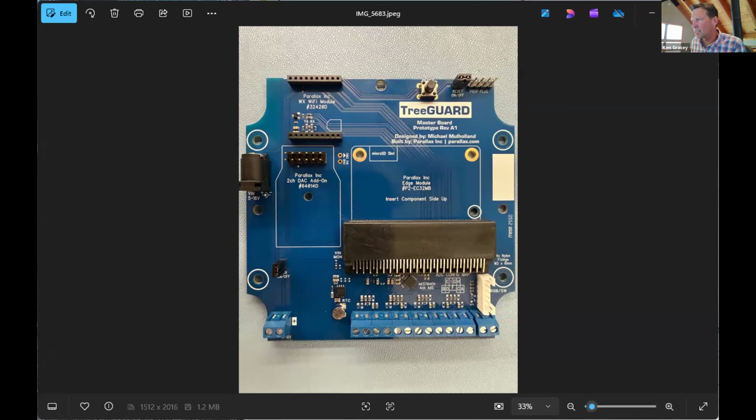And we added an ADC, right? We did not use the P2. Right. So Michael Middleton integrated what was on the ADC chip from AKM that you guys already had as a board that would plug into the breakout board. And so that's at the bottom of this board, and you can see the screw terminals where we can bring signals into the ADC. It's an ADC that goes up to 192 kilosamples per second, which we really wanted for this project because we wanted to be able to get sounds up to 35, 40 kilohertz.